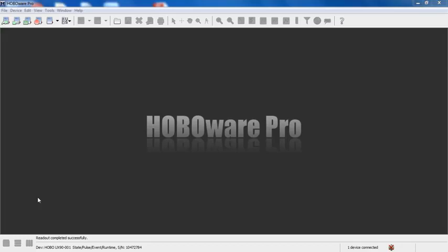Onset sells a couple of different types of these devices, specifically the WattNode device from Continental Controls, and also the Veris kilowatt hour transducer that outputs pulses. So we give you the ability, both at the time of launch and when you read out your data, to scale those pulses or those counts into energy, kilowatt hours, and calculated power based on what your logging interval is.